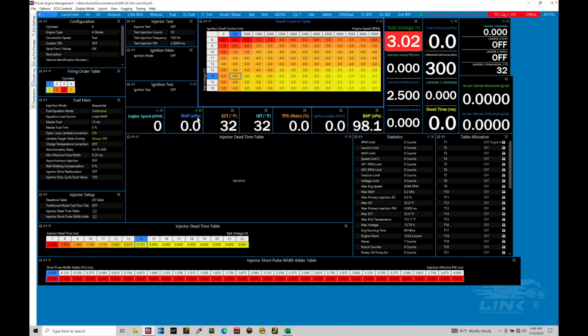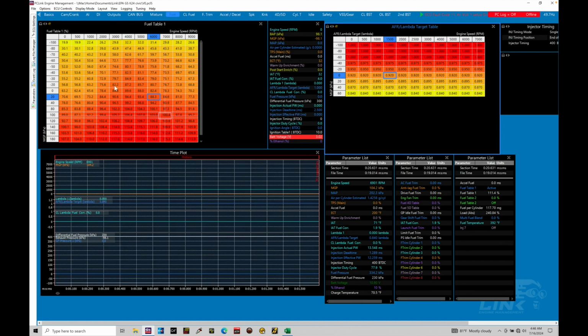Now, when we get started with the traditional mode, the default value is always here at 15 milliseconds, and then the table values here are something that we don't know. They have to be worked out. Ideally, we'd like to see ourselves at idle, let's say right in here in the idle range, vacuum engine speed, around 40, 50, kind of the similar idea as what we talked about in volumetric efficiency. And then as we get up here into positive manifold pressures, we like to see ourselves in the 100 to 150 range. Now, these values do not represent cylinder filling, so they're not going to be part of any air mass modeling that we find in the modeled system. It's purely going to be a percentage multiplier to that main fuel value.